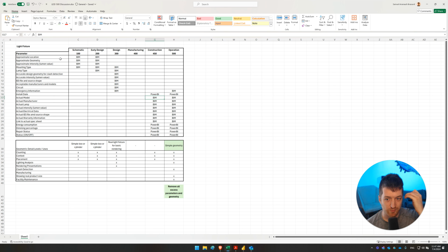And when you're in construction, usually you want to start thinking about the as-built. Well, you definitely want to start thinking about the as-built, at least for operation, right? So it's no longer a generic light that could be this or this or that. It's a light that's been actually purchased, that has a specific model, a specific clamp, a specific lumen, a specific intensity and IES file and shape and warranty and energy consumption. So those things are specific and no longer up in the air, and we can determine what it is. Vice versa, there are probably a lot of parameters that are no longer useful.